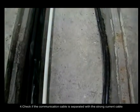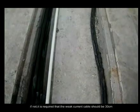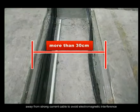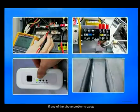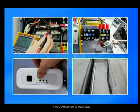4. Check if the communication cable is separated from a strong current cable. If not, it is required that the weak current cable should be 30 centimeters away from the strong current cable to avoid electromagnetic interference. If any of the above problems exist, it must be modified. Then the malfunction can be solved. If not, please go to the next step.